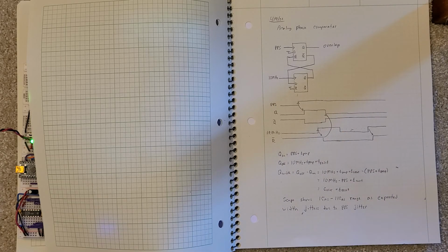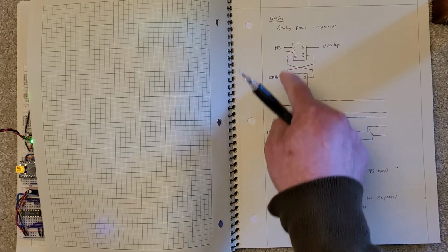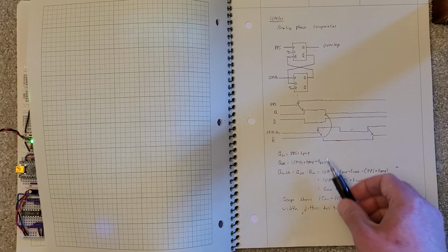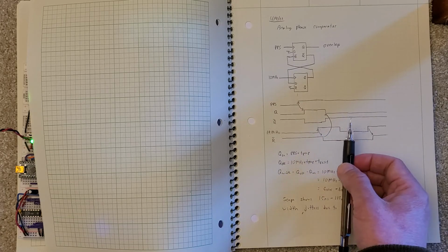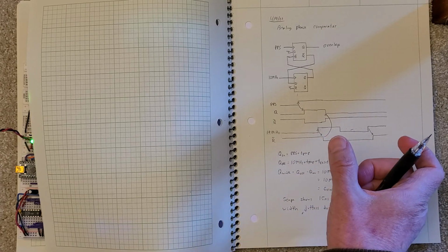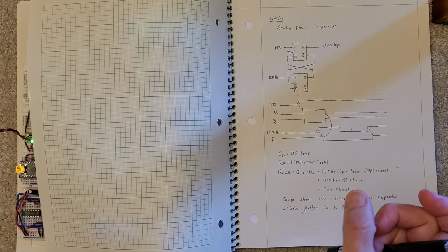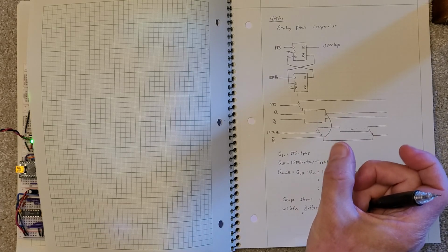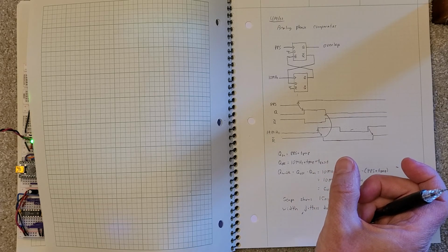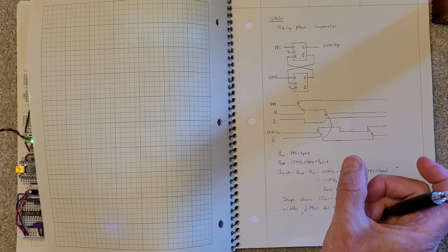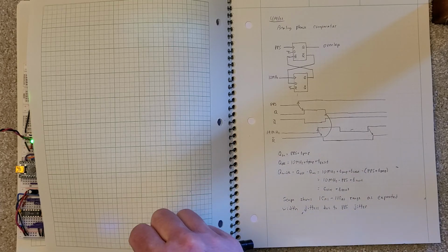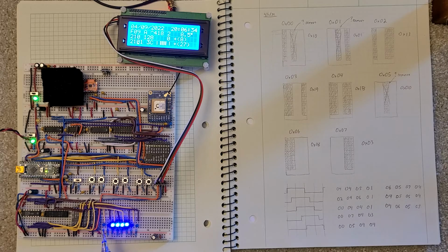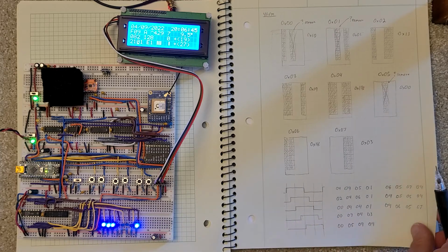So the pulse width, normally the difference between these would be between 0 and 100 nanoseconds. Since I have the reset time in there, the pulse width is between 15 nanoseconds and 115 nanoseconds. And that will have a jitter to it, and it'll also grow or shrink depending on what the actual offset is. And so if I look at my display here, what I'm actually measuring is the distance between this LED and the first lit one, not a position of the edge.